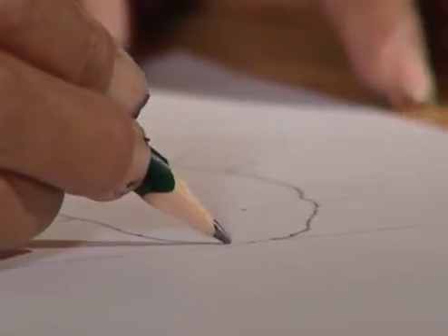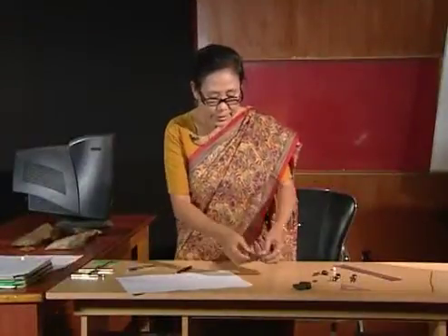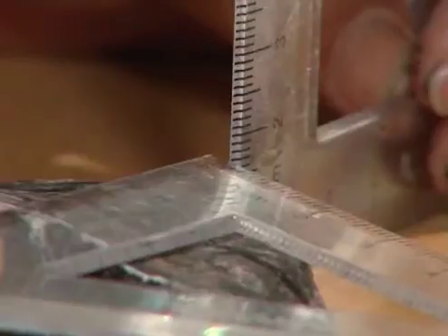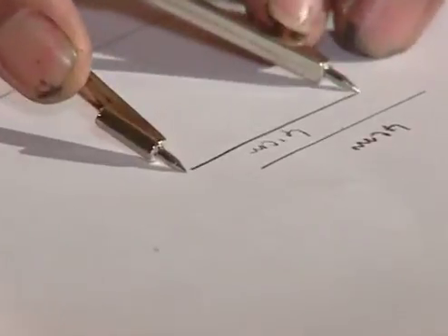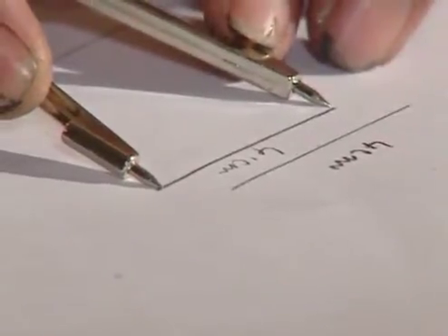The 10th point is, the 9th step is the removal of the lithic tool from the drawing sheet. The tool is then placed properly with the apex on plasticine on the practical table again without changing the position already drawn. 11th, the next step is taking the accurate measurement by using either two set squares and a divider or a compass and two dihedrons, that is a folded index card, or both.